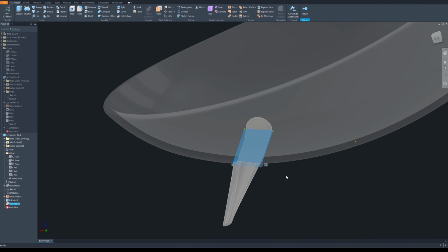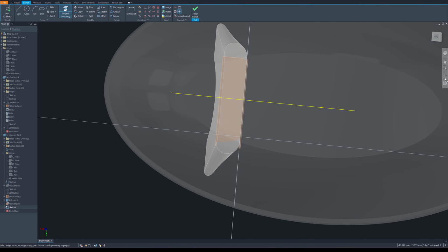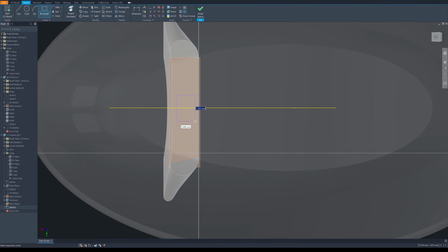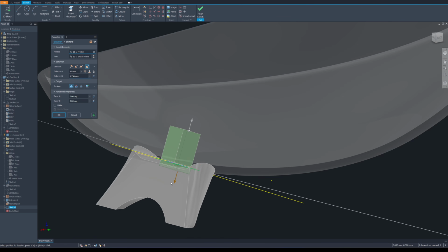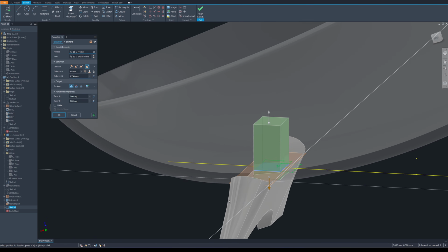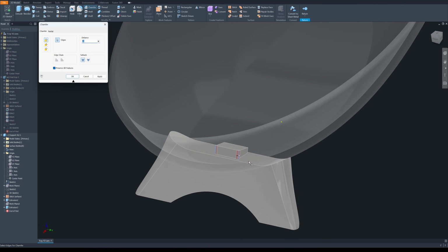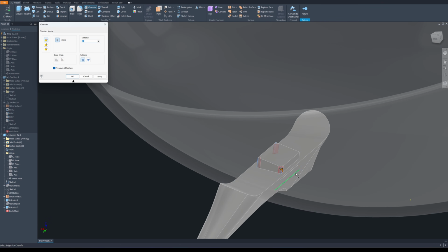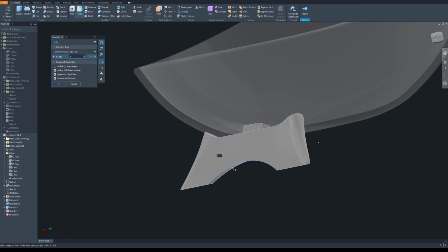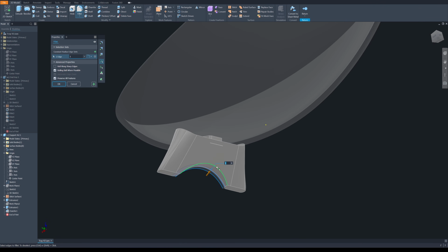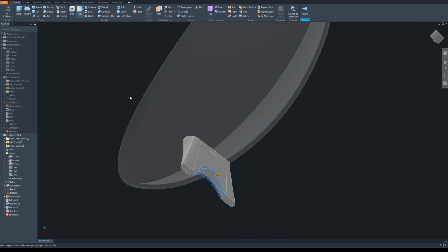Next, I'm going to create a plane on the leg support and draw a small rectangle. This will be the alignment key, so that I can align it after I apply the adhesive. I add a small chamfer on the corners for easy fitting. Add fillet along the edges.